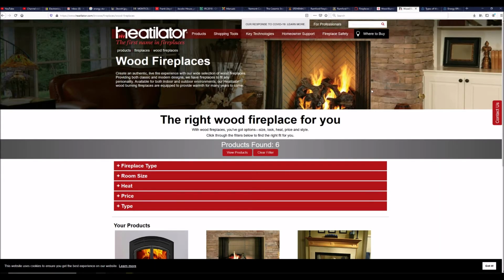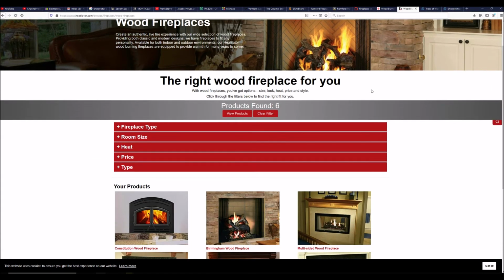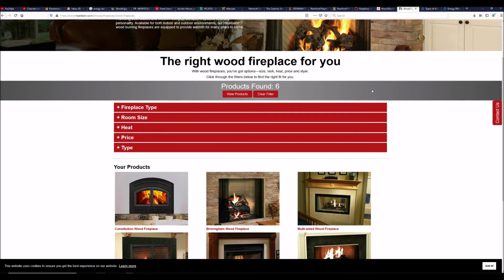So that's a great route to go down. Then you only need to have a metal chimney. You don't need to have a masonry chimney, and you can sidestep all those issues of earthquake and wind loading on the chimney. They do have their own clearance requirements, and they can take up a considerable amount of space for that.